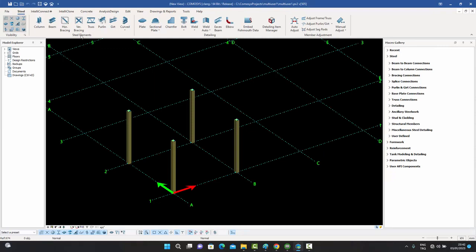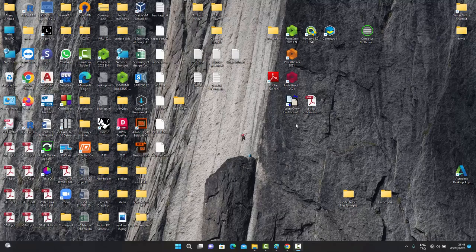And the moment this is done, if you notice, these two new buttons appear at the top, which previously did not exist, telling us that this is now a multi-user model, and we can retrieve from the server, load updates from the server, or we can save changes to the server. These two options will then synchronize this model with the server. So now we are in a situation where user 1 has created a model called multi-user 1 and has shared that model with the server as the owner of that project. So user 1 is the owner, and user 1 has put that project onto the server.